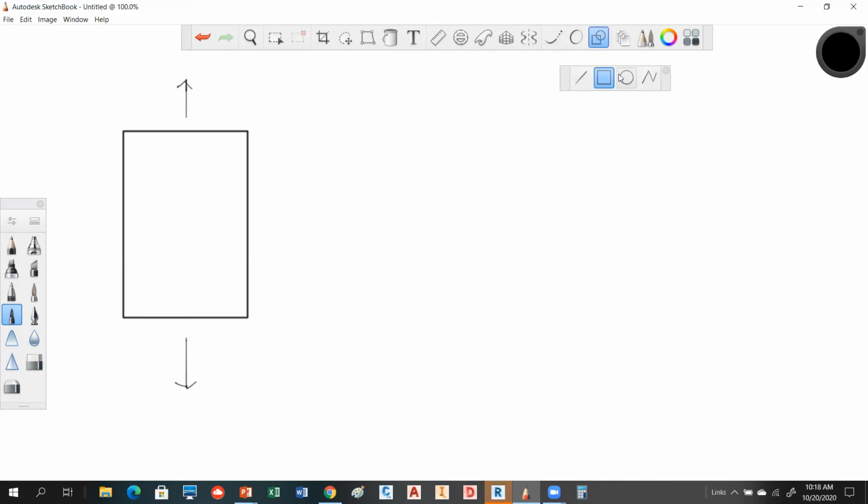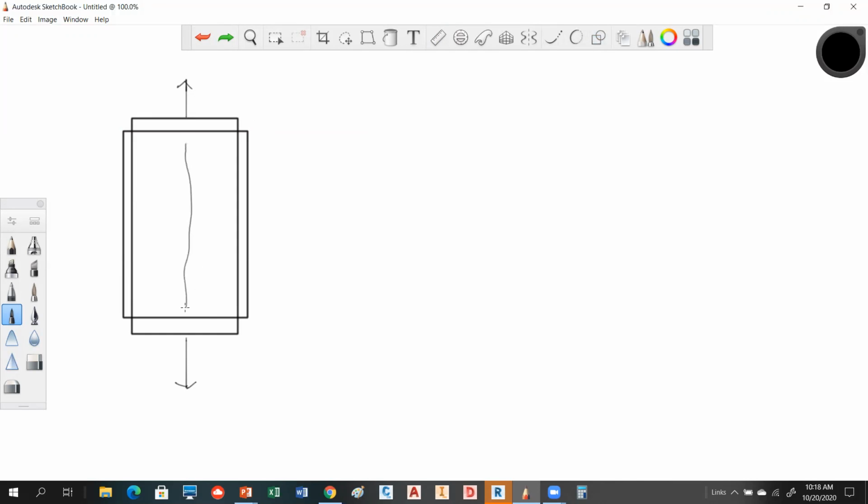So what's going to happen to this? It's going to elongate. It's going to get longer this way, but notice because it's elongating and volume is staying the same, it's getting smaller in this direction. So this is your axial direction, or your primary direction, and this is your lateral direction. Notice, in tension, because this is a tension force, this cylinder started out originally that way, so it elongated, but it's compressing this way because the volume's staying the same.